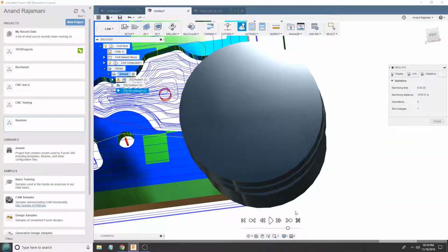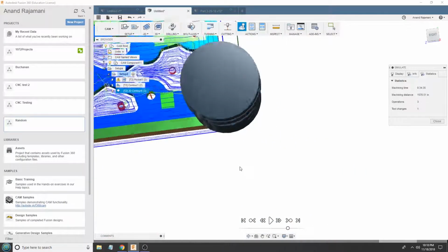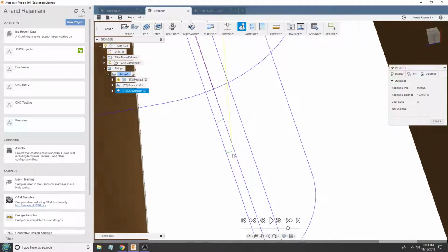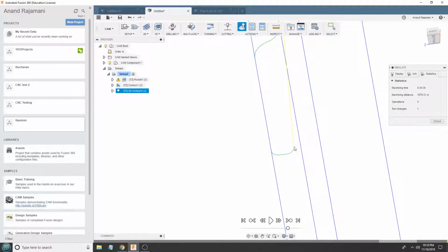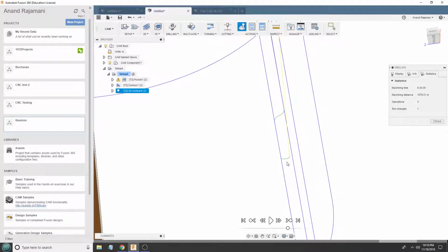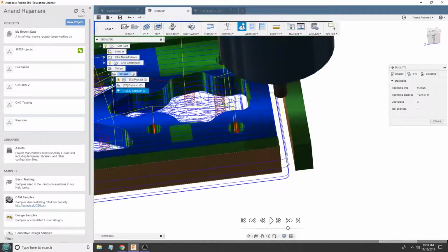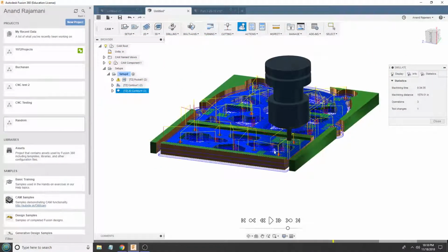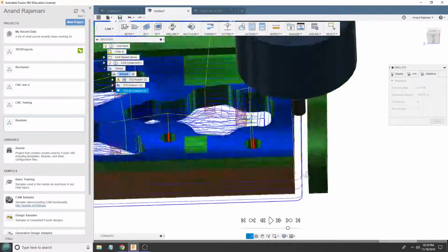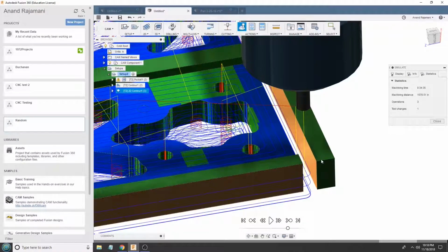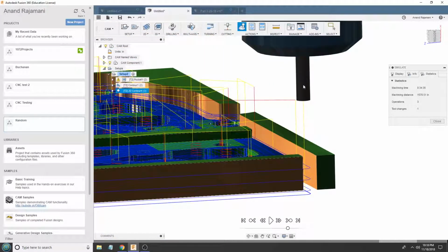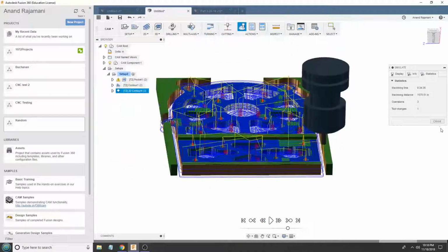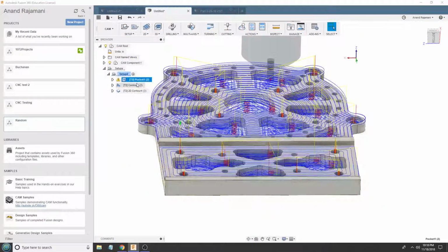And you can see right at the end there, well, let's see if you can see that. Right at the end there, we do have a teeny tiny lead out right there. And that's just enough to stop us from gouging when we come out. Because otherwise, you leave this vertical tool mark right here, which is very noticeable and kind of annoying, actually. But if you have too much of a lead out, then you just bite straight into a 1/2 inch thick piece of plate with your 1/2 inch long end mill, and you're like, why did I do this to me? It's very sad. So anyway, that's that. And there you have it.